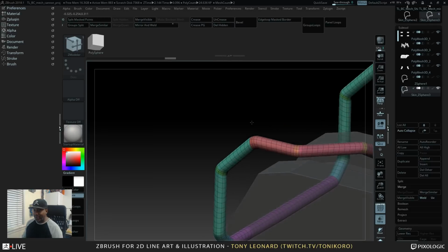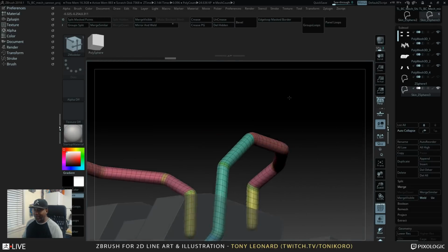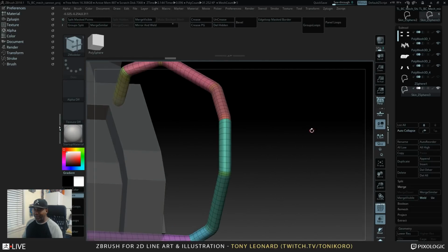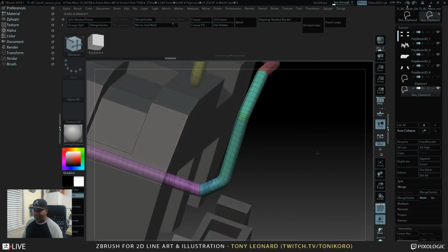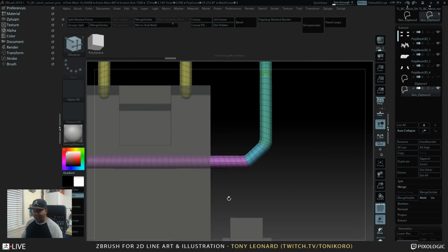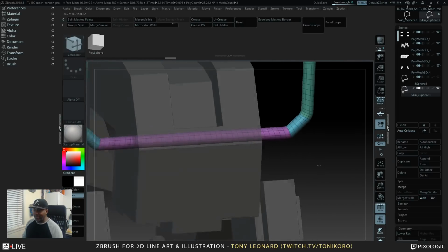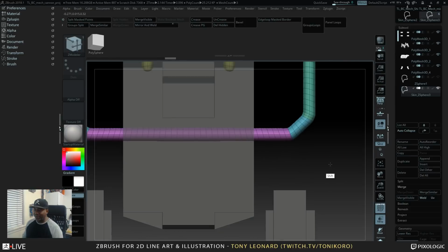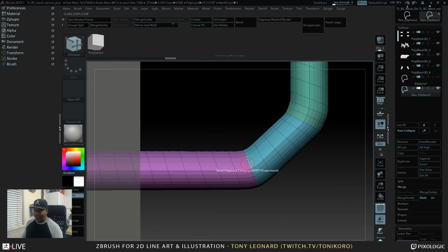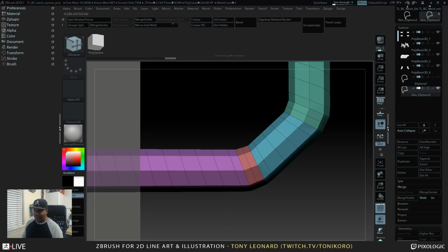It'll soften it out, and then you have your pipe. You just use a bevel to increase the resolution of the bend, basically, and it should come out pretty alright. Some spots may or may not meet it. I suppose it depends on the severity of the normal angle, but I'm just gonna put them in anyway. Create some nice soft bends there.